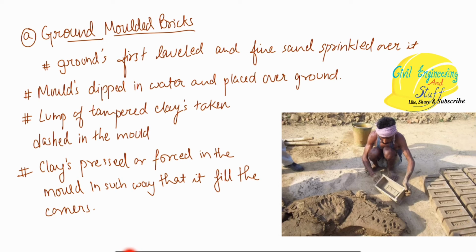It is to be ensured that the prepared clay is free from any lumps, because if lumps are there, then the bricks that we will get, or the framework that we will get, will have pores in it, right?